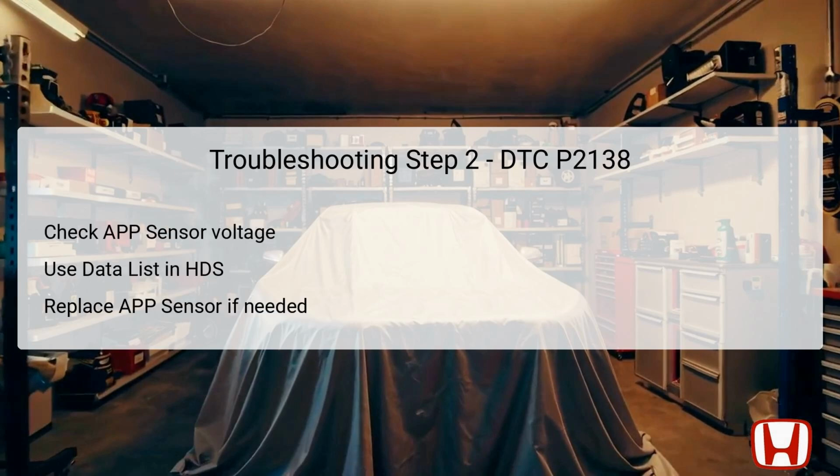In the second troubleshooting step, focus on the APP sensor signal check. Using the HDS, access the data list to inspect the voltage readings from both APP sensor A and APP sensor B. It is crucial to verify whether these voltages are the same. A disparity suggests a fault in the sensor. If both sensors show matching voltages, proceed to step 3. However, if they do not match, it indicates one of the sensors is likely faulty.